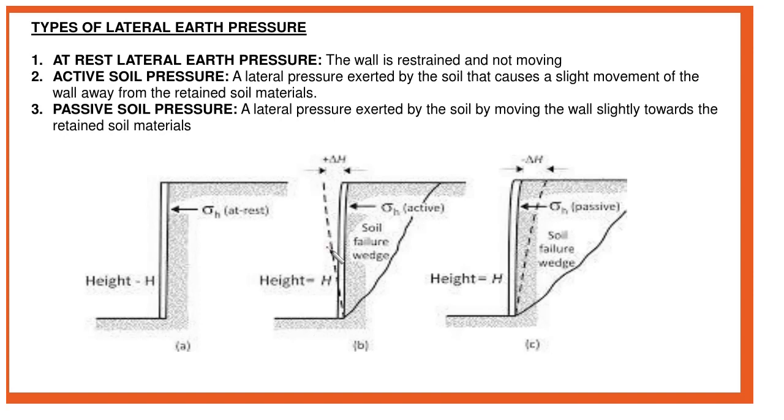So we just have a soil all by itself sitting, we call that at rest condition. Say if the wall is rigid and does not move with the pressure exerted on the wall, the soil behind the wall will be in the state of elastic equilibrium. Kaya at rest pa rin yung ating condition dito. So, we have at rest lateral earth pressure.